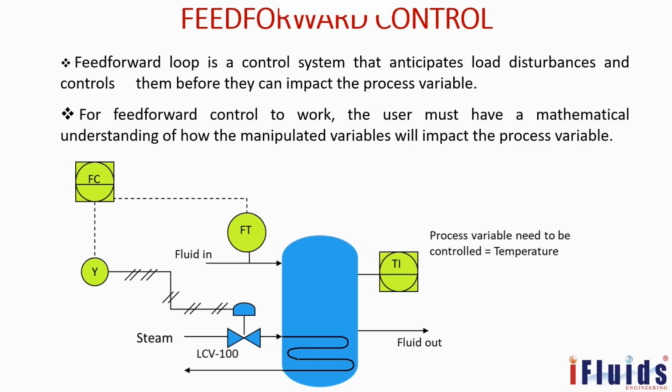Normally this feed forward control is an anticipatory control. We call it anticipatory control. In the PID algorithm, proportional, integral and derivative will be used in this control, because in temperature we will not sense the change immediately. It will take time. For example, if the temperature is 90 and it goes to 95, it takes a little bit of time. If you take action immediately, then when it reaches 95, there will be oscillation in the system. It will not be controlled.